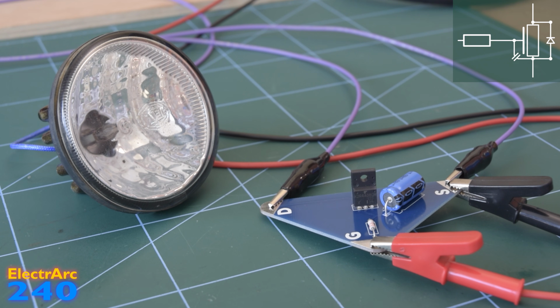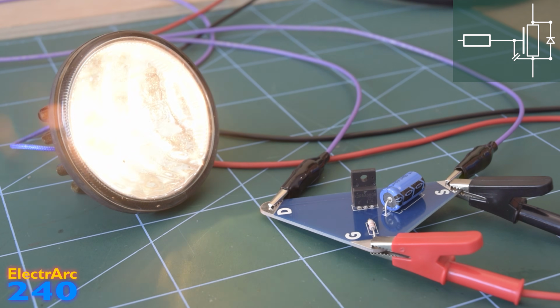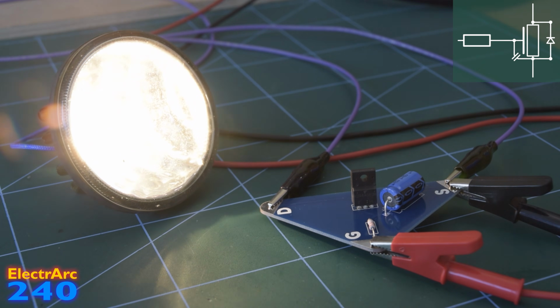So here we have, once again, the simple low-side switch circuit, with our lamp and our MOSFET, though this time it's the MOSFET with the gate capacitance. If I now turn on the gate supply, we'll notice two things. First off, there's a delay. The lamp hasn't turned on yet. And secondly, when it does start to turn on, it takes time to turn on,